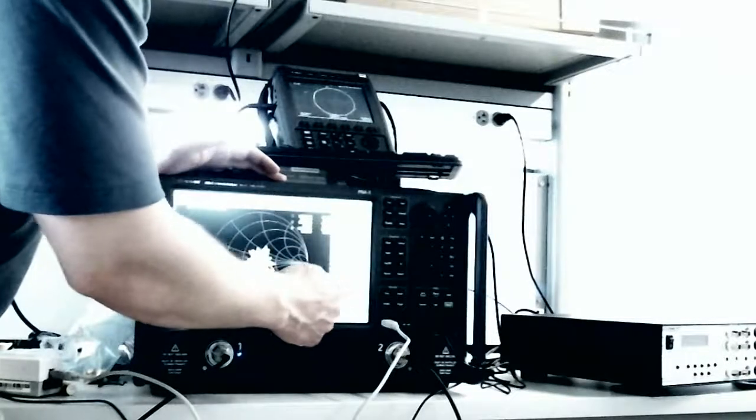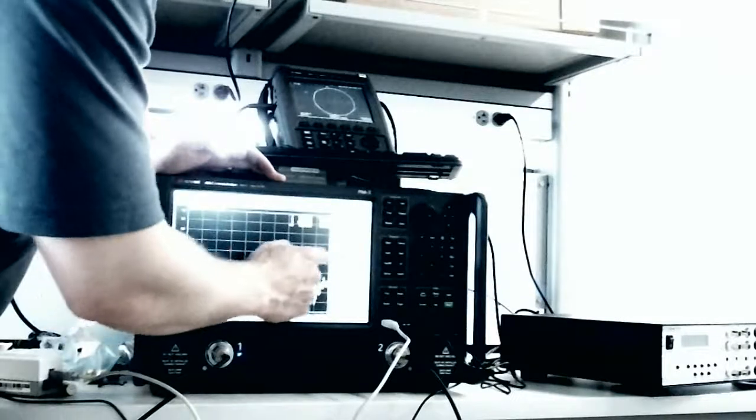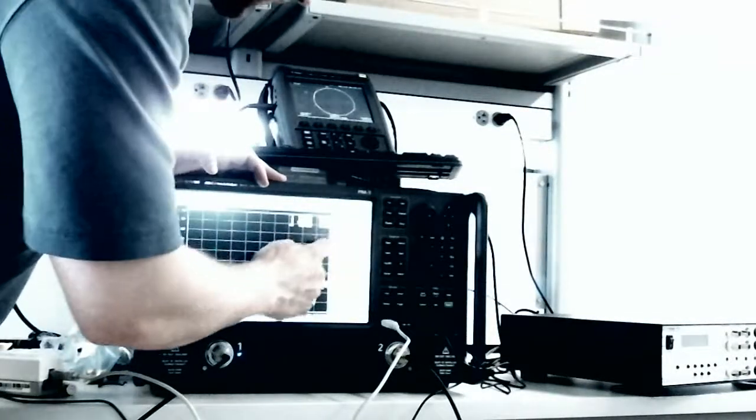So if you go to format here, you can go linear magnitude, we can do the math there, and we can do analysis, conversions, Z reflect, and this is the linear magnitude, right? That's the 47. Let me see, let's go to trace, inside another trace. We're measuring S11, we'll go to format, and instead of linear magnitude, let's go to imaginary.